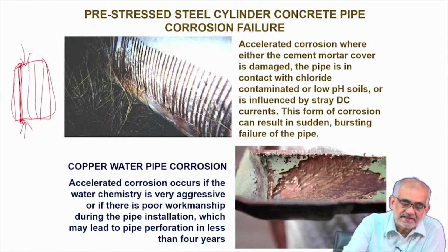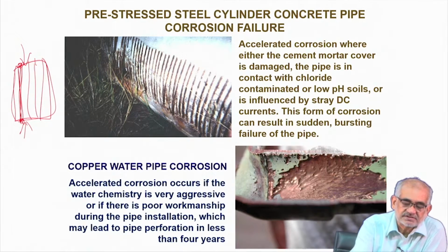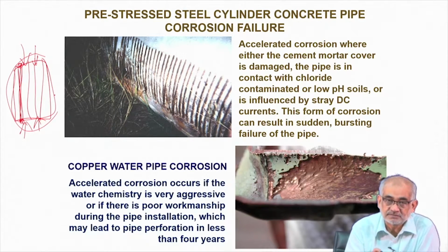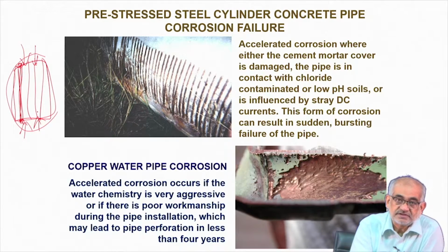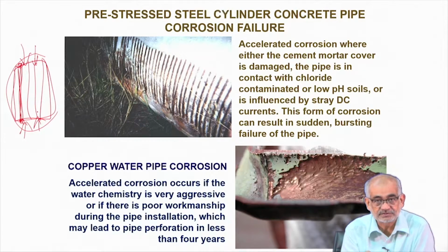So when they try to relax, then they try to actually stretch along with the concrete, but by then the concrete is all cast and frozen, so it cannot allow the rods to stretch anymore. So in the process it develops a residual stress on the surface, which acts in opposite direction or compressive in nature. Now even in order to get this effect of residual compressive stress, use of such reinforcements which actually produce residual compressive stress is very important.